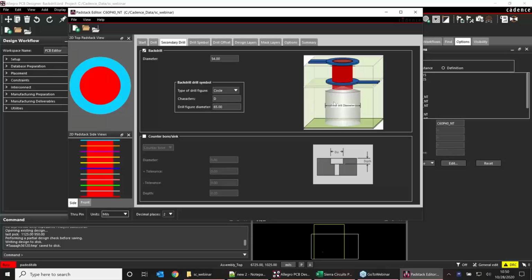And the tool is able to figure that out itself, how far it needs to drill based on the layer that it's coming from and going to. It knows which type of back drill to use to make that effectively work without ruining the trace that you're trying to still use. So this is how you can visualize that it's happening and verify the distance that it's drilling.